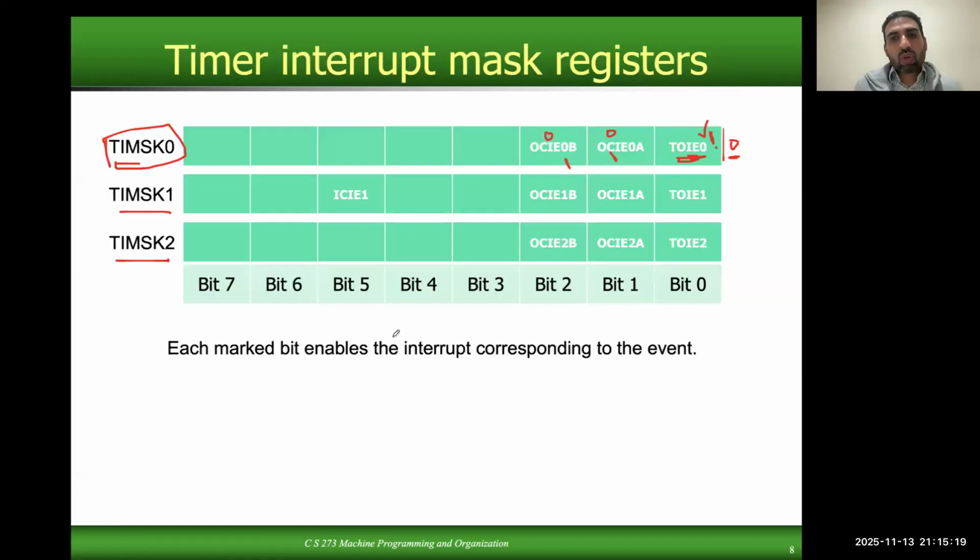So if you are enabling the interrupt, you must also write an ISR. Otherwise, if the interrupt happens and you have not placed any valid code there, there is garbage, and your microcontroller will start executing garbage.